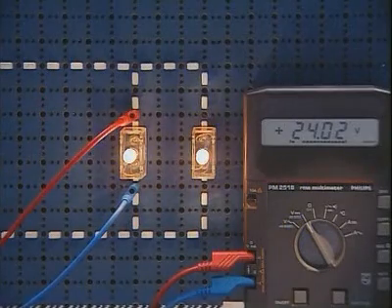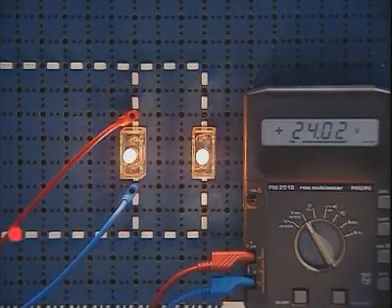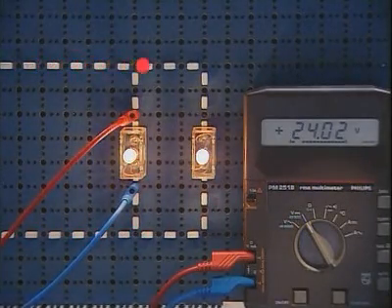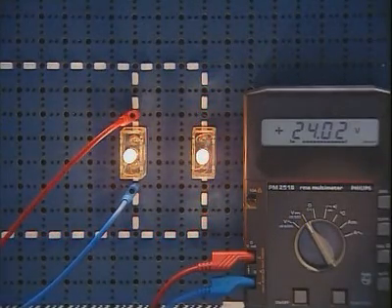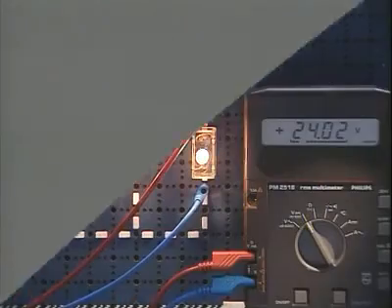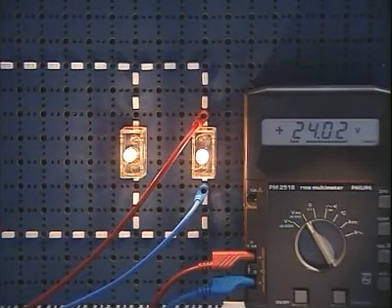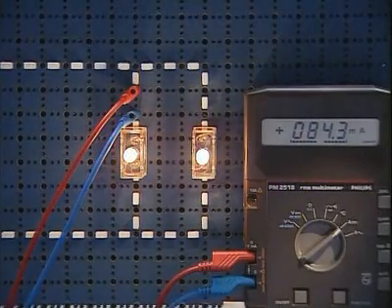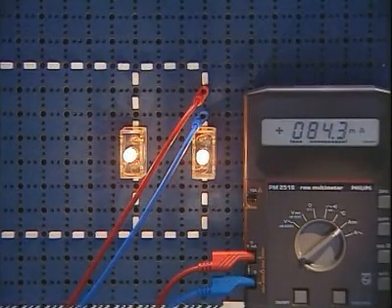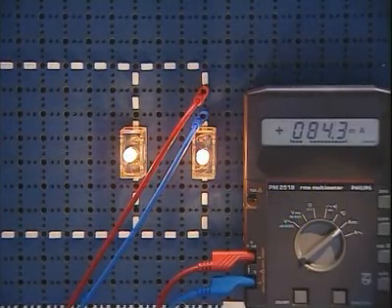As we can see, the parallel circuit is different. As each lamp is practically connected directly to the voltage source, the full voltage is applied to each load. And the full current flows through each lamp. Both glow brightly, as did the single lamp at the beginning of the experiment. For this reason, loads in electrical systems are normally connected in parallel.